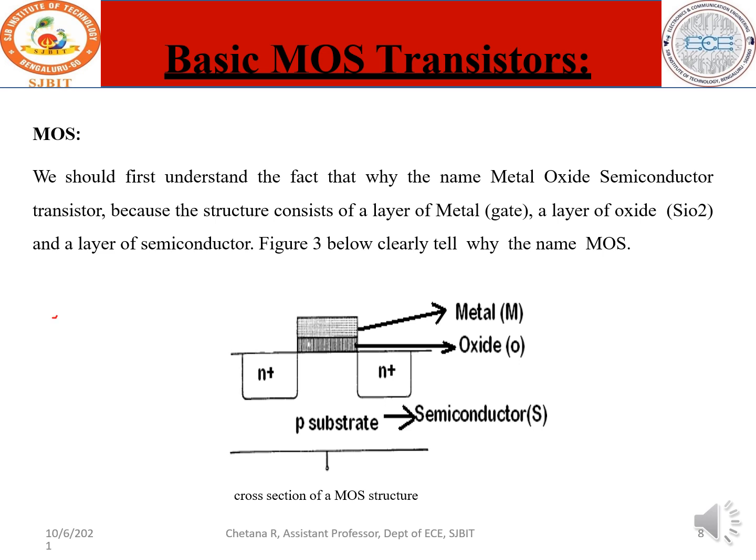So you can have it like this. This is your metal, this is your semiconductor, and in between you have your oxide. So what is this device? This is nothing but your capacitor. Doesn't it look like a capacitor? Two parallel plates filled with an insulator. So the insulator here is the oxide, and this one layer here behaves as your metal, which is polysilicon, and in the bottom you have the semiconductor, which is S. Therefore we have MOS or the MOSFET.